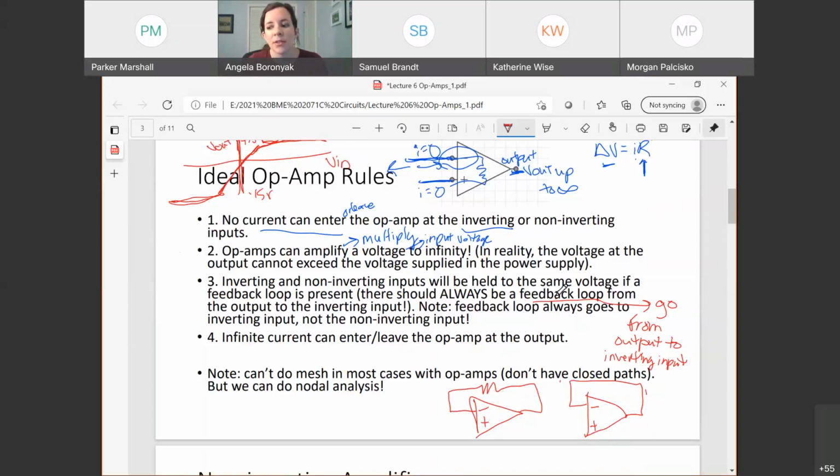And if you're trying to set the thermostat for your house, what it's doing is saying, okay, I've set it to 76 degrees maybe, and it has a plus or minus 2 degree range that it's okay with. If it goes above 2 degrees over my set point, so from 76 maybe to 78, I measure that on my output because I'm sensing my temperature, and I compare it to my desired input, which was 76. Comparing it means I'm subtracting, or taking the difference between those two and saying, hey, is that more than 2 degrees off from what I wanted?